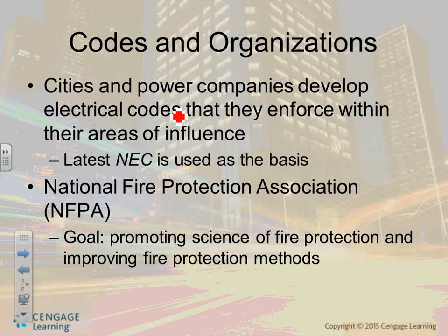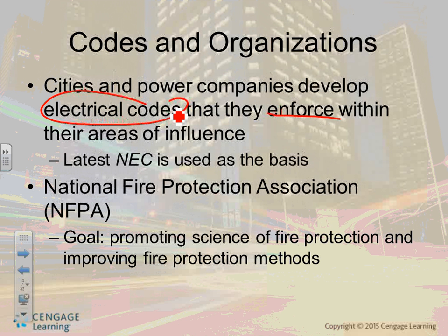So cities and power companies also can enforce and develop their own code. So you're going to see, like I believe in Chicago, you can't use Romex. The city of Chicago requires you to use EMT when you're wiring residential. So not just because you know the NEC code book, in Minnesota you're safe, because most of the time we adopt the NEC code book as is, we don't modify a whole lot. You go to other places of the country, either they don't adopt it, or they add to it, like in California. So when you become a big project manager and go work in California, make sure you become familiar with their code.